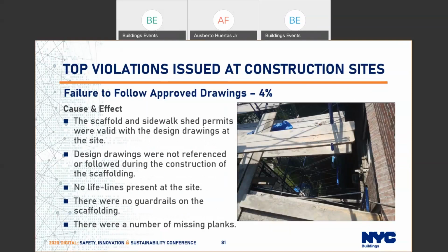Although the scaffold and sidewalk shed permits were valid and the design drawings were on site, the drawings were not followed during the installation of the scaffold. The scaffolding installed was missing guardrails and planks. Additionally, lifelines were not present.